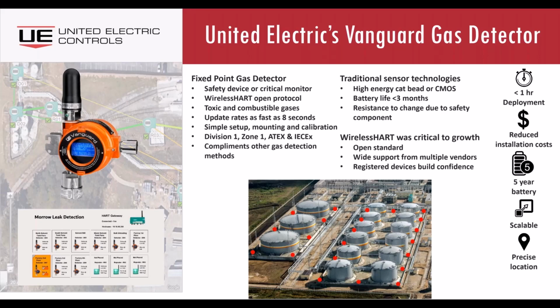And then, if you design it as described, it's interoperable with any other manufacturer. There are 15 manufacturers that are registered to work with WirelessHART. So now you can plug in a detector anywhere there's infrastructure. And that has given a lot of confidence to the industry to start applying these in a safety application such as gas detection. And you can scale them up pretty quickly.